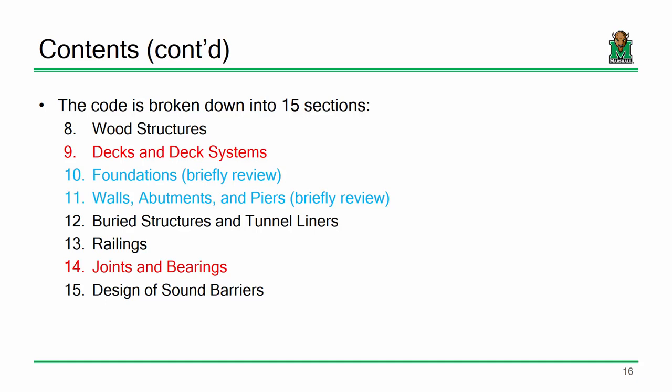The elastomeric bearing is the device that transmits the load from the beams to the abutment. Elastomeric bearings are a very common device. There are other ones out there, but for these types of bridges, elastomeric ones are arguably the simplest way to go. They allow for a significant amount of movement of the beam, which is really nice if you've got thermal expansion and contraction to consider and other things like that.